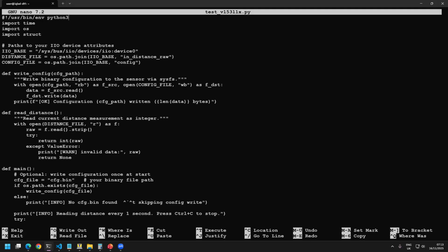One more thing. One of the challenges in the older IO driver was loading the configuration during the run. That can be overcome using this technique. So we can basically perform the open, read, write. These are all system calls. So using this open function, we can transfer the binary, the configuration, to the target.